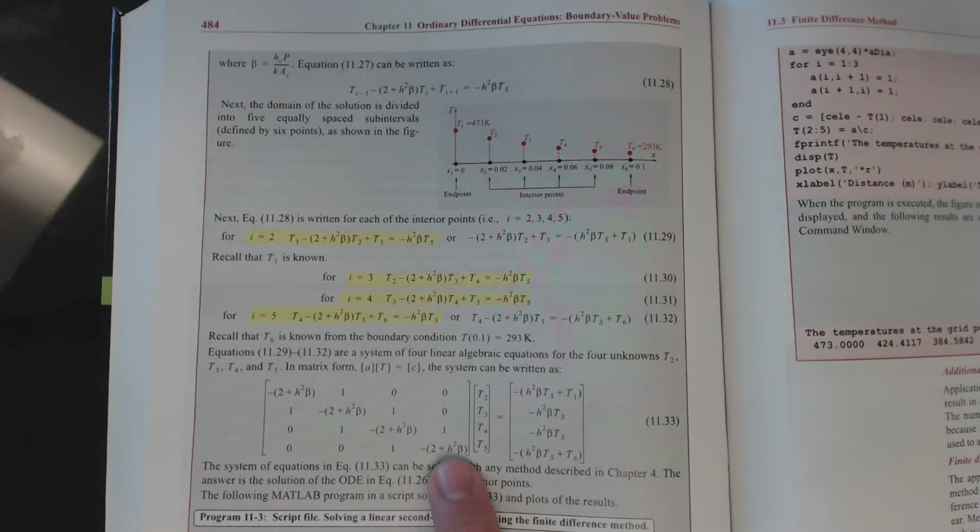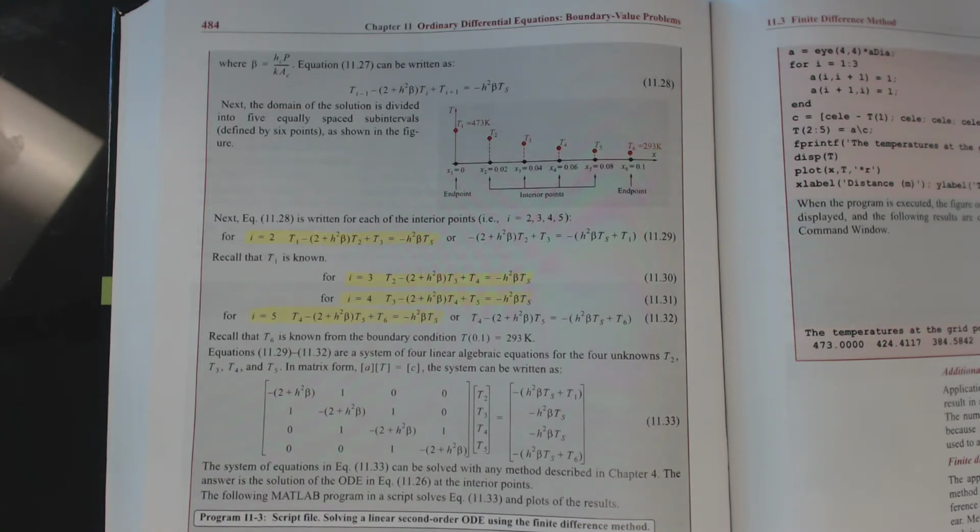So you stay in the linear elastic region of the material model. Solving it in a linear elastic form allows you to use matrix inversion and directly solve for the unknowns. That's why those linear FEA problems are very fast in solution. Even if they have many, many points, they more or less just invert the matrix, solve, or they use who knows what matrix solution method is behind the scenes in those actual codes, but they find a direct solution of the matrix and present it.